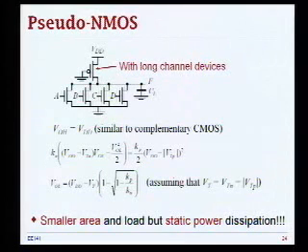Now, what you need to worry about is basically static power dissipation and ways you can cope with that. Obviously, you would like to size this transistor as large as possible from the propagation delay standpoint, but you also need it as small as possible to conduct the least amount of current when the pull-down network is pulling down to 0. That's sort of a compromise. Another good thing about this is that the total self-loading capacitance at the output is now reduced, because you have fewer transistors connecting to your output.